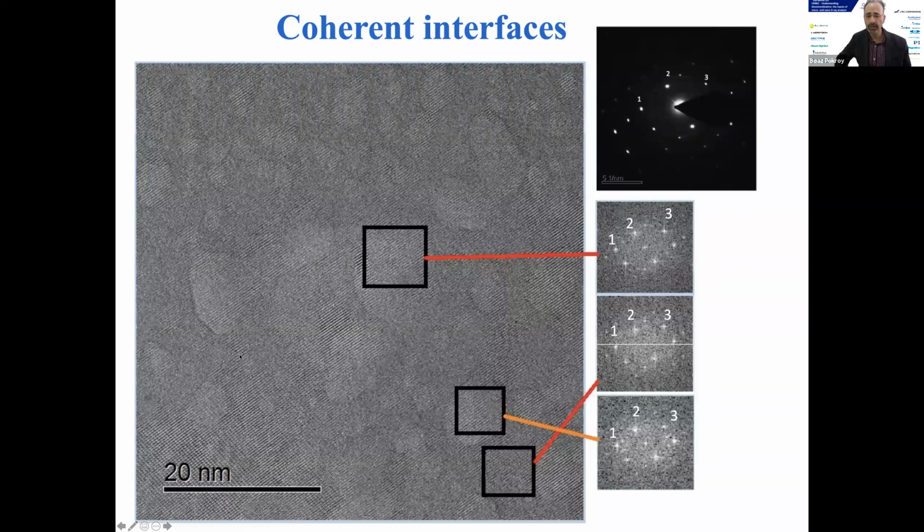So we have a huge single crystal, and inside you have all these nanoprecipitates, which are richer in magnesium compared to the matrix, and they are completely coherent, which we saw on ID22 by having this nano hump beneath the diffraction peaks. And again, here you see this in high resolution TEM.